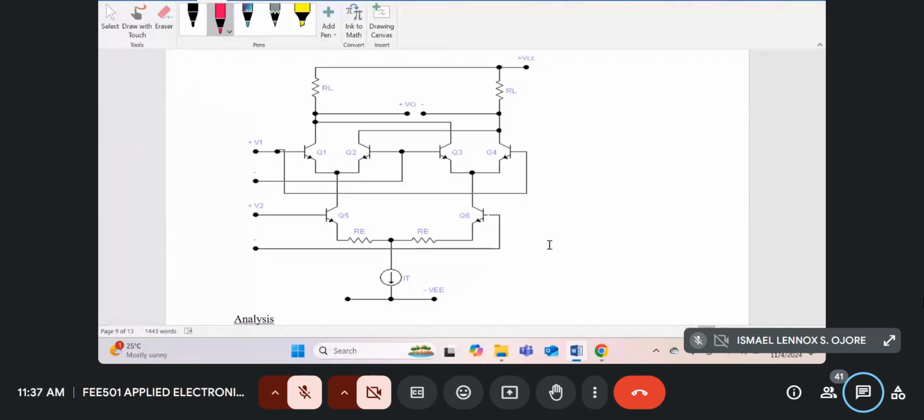Now for this circuit to work, Q1, Q2, Q3, Q4 must be matched transistors. The best way to get transistors matched is to fabricate them at the same time in one chip. And also Q5 and Q6 must be matched transistors.